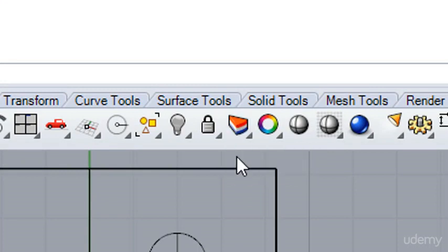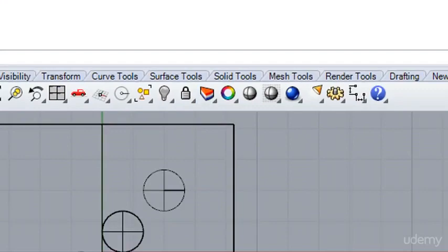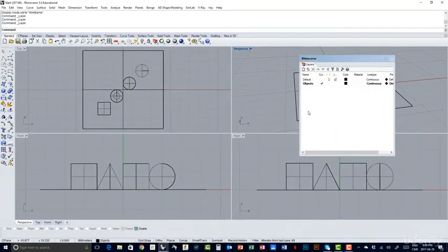window. It's called Edit Layers. So just bring the left cursor and activate this one, and it's called Layers. This is where you're going to be able to separate your different drawing surfaces into different layers and have the work environment very organized.